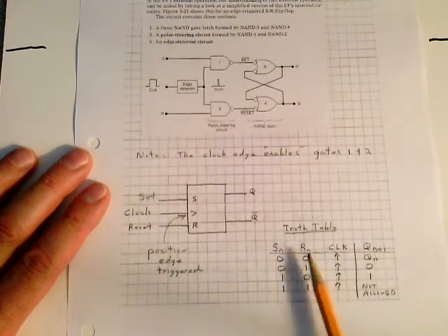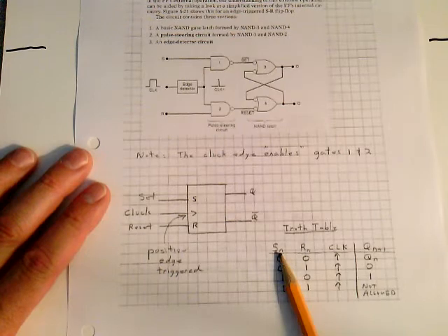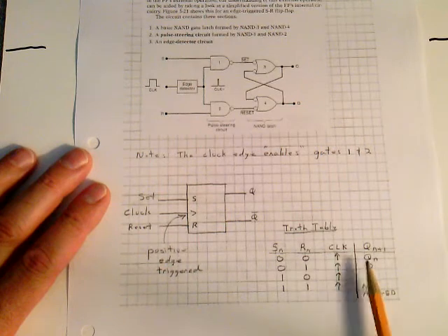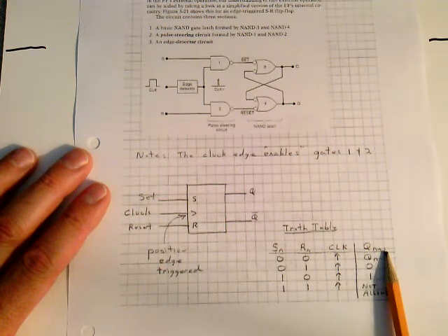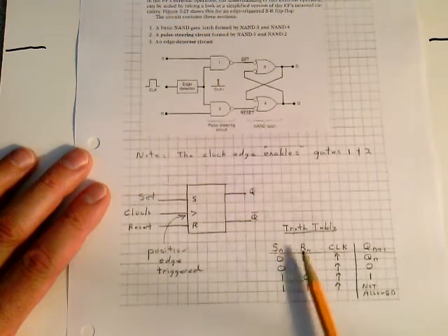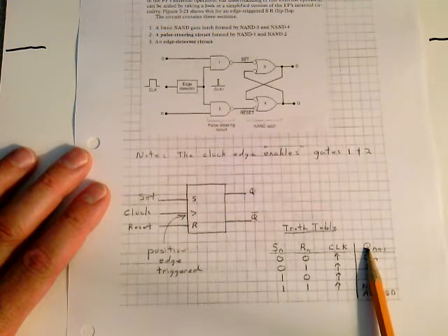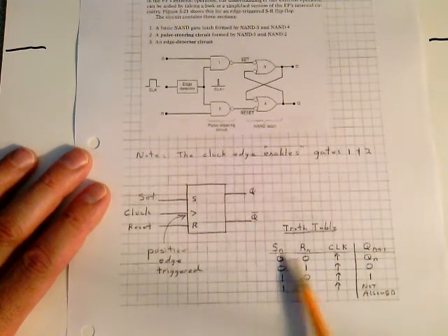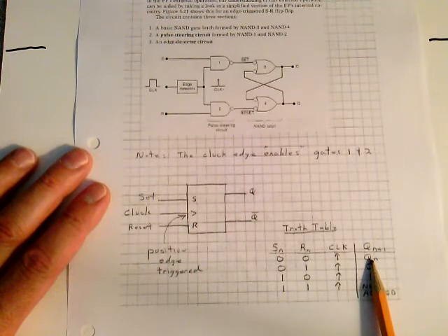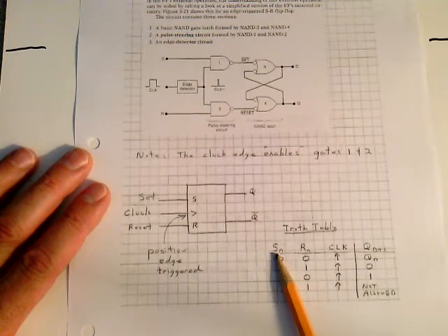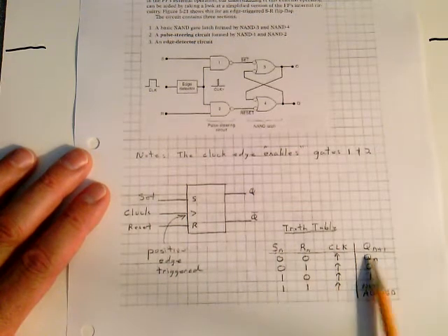Look down here. On the nth clock pulse, whatever it is, when the clock pulse comes, if it's 0, 0, the output's going to be no change. Q sub n plus 1 comes on the next clock. Here's S sub n and R sub n, set up on the nth clock. When the next clock edge comes, you get the output Q sub n plus 1. If there's no change at 0, 0 on the clock edge, that's Q sub n. The output is whatever it was back when you set up the S and the R on the nth input. That's why they call it Q sub n.